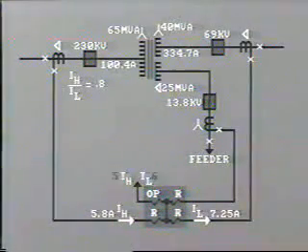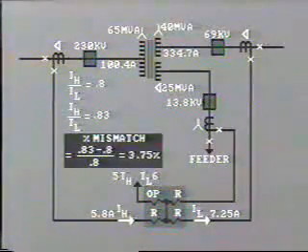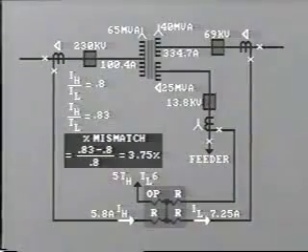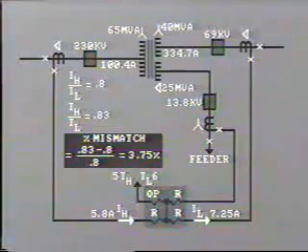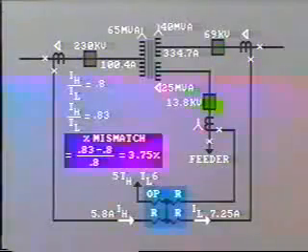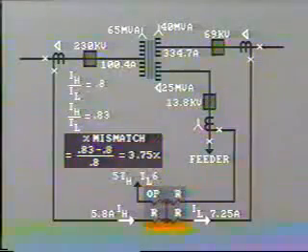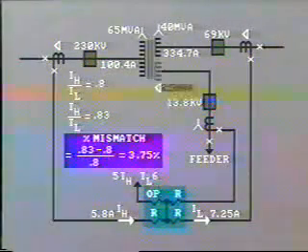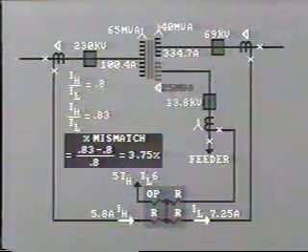Now, let's suppose that our taps are set on 5 and 6 respectively, giving us a tap ratio of 0.83. Our mismatch can now be calculated as 0.83 minus 0.8 divided by 0.8, which equals 3.75%. This is well within the transformer differential relay restraint setting. A similar calculation would now be made for the tertiary, using 25 MVA as the base.